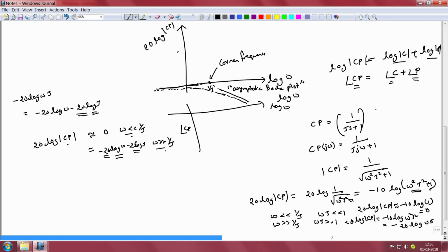What this reveals is that if I were to simply draw the magnitude characteristic, I do not really need to take extra care to also draw the phase characteristic. I can derive the phase characteristic directly from the slope of the magnitude characteristic at each of the frequencies. Of course, this relationship is only approximate, but the degree of approximation is generally quite good in most cases.